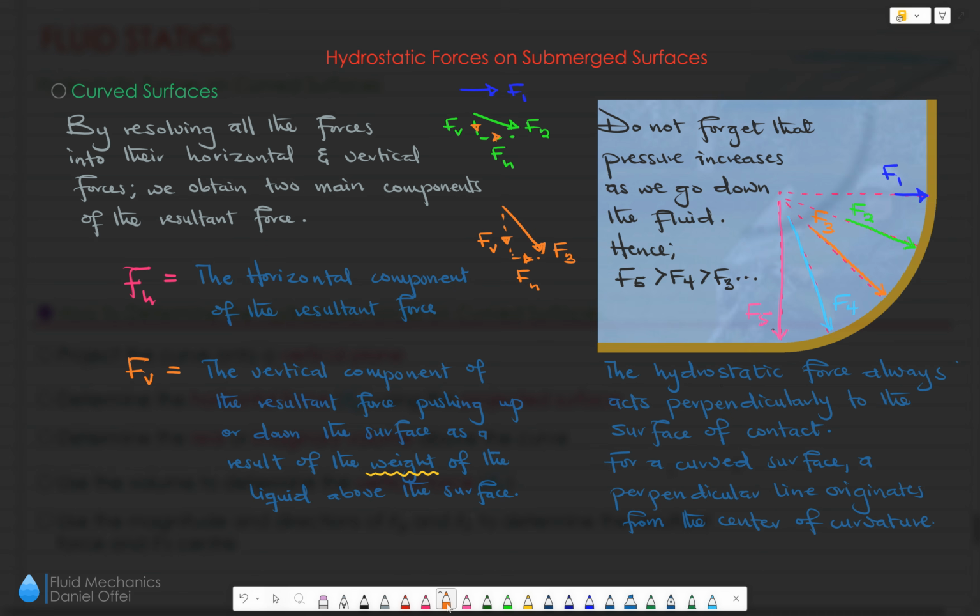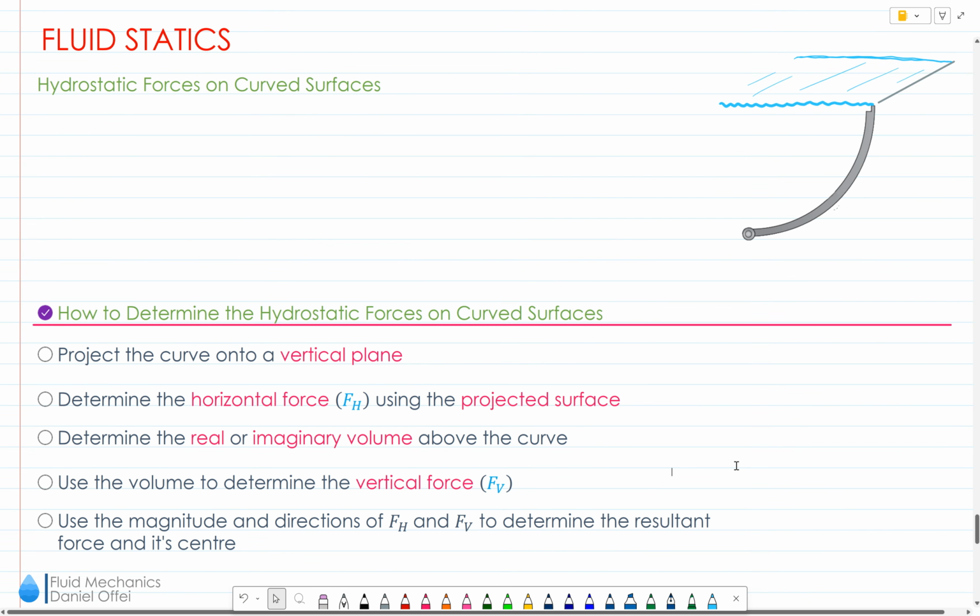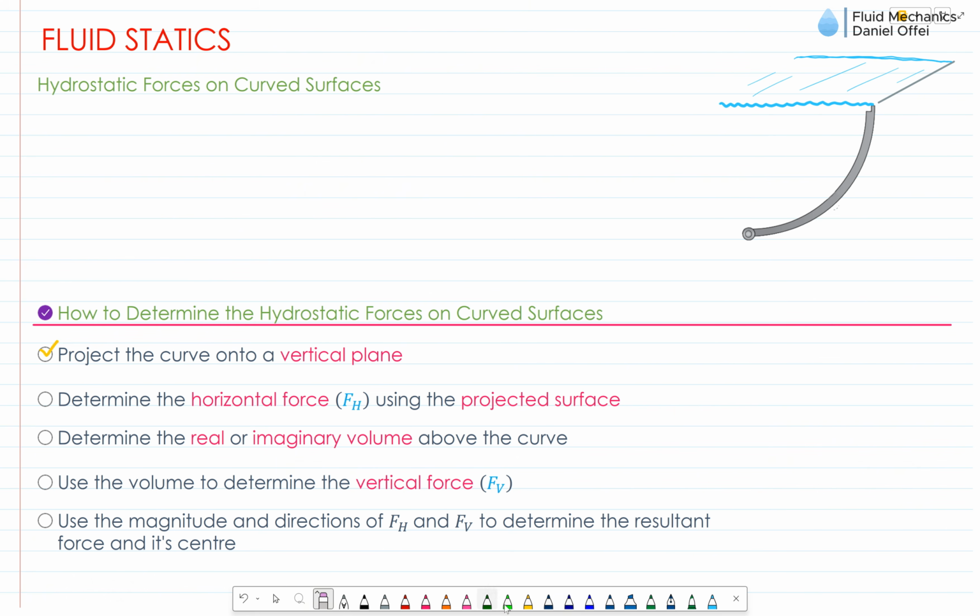Now let's go back to the notes and then see how to deal with curved surfaces and how to solve questions on curved surfaces. To determine the hydrostatic forces on curved surfaces, we do the following. The first one is to project the curve onto a vertical plane.